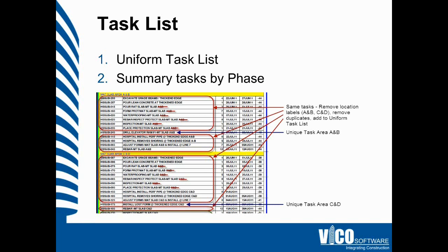It's an important one to understand in this context, because it's the second differing factor between a CPM schedule and a flowline schedule. The first is the location breakdown structure, the second is how the tasks are represented. In this case, with drywall, maybe there are 10 individual activities for 10 drywall locations on the job. Each one of those is going to have a unique ID.